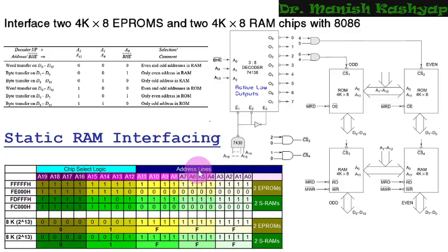And by mistake, I have written address lines till 11th. However, it should go up to 12th, because we have already discussed that 13 address lines will be required. So from A0 to A12, these address lines should extend up till here, and the remaining bits, that is from A13 to A19, will be used for chip select logic, right?